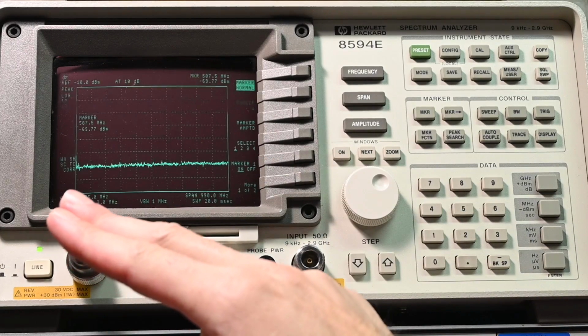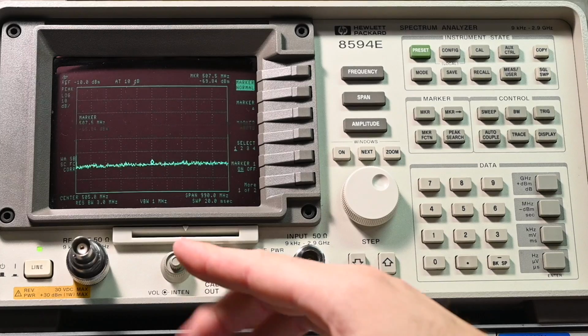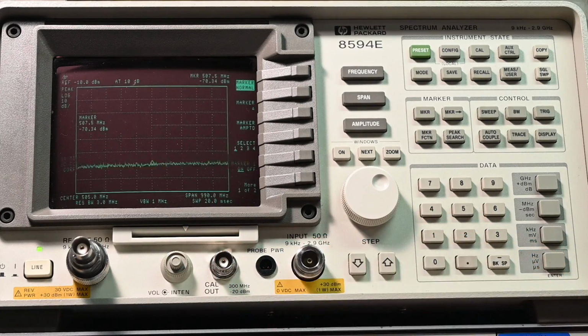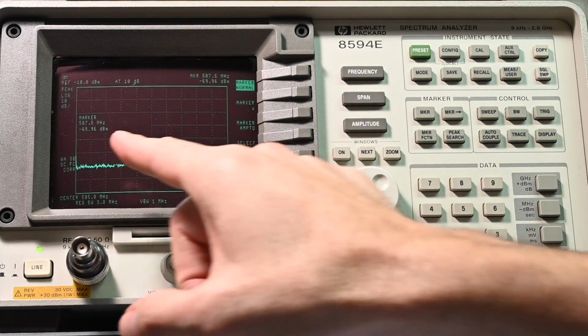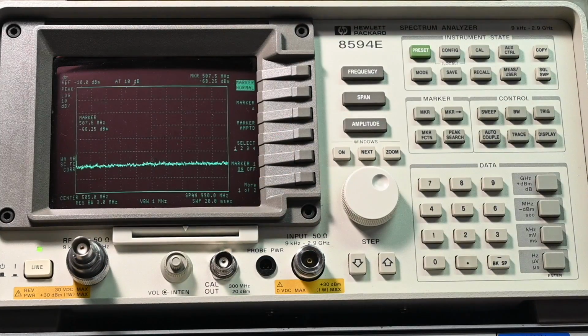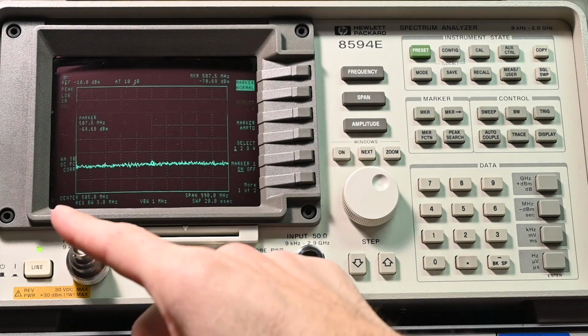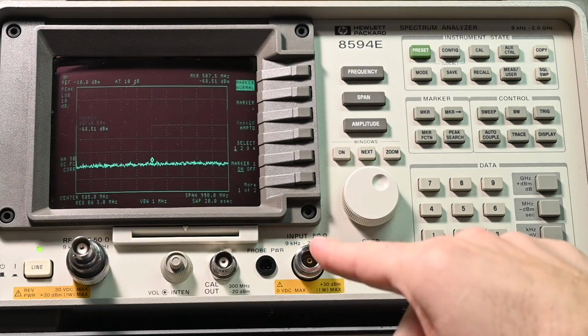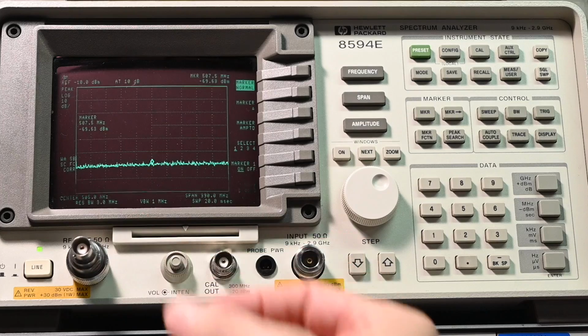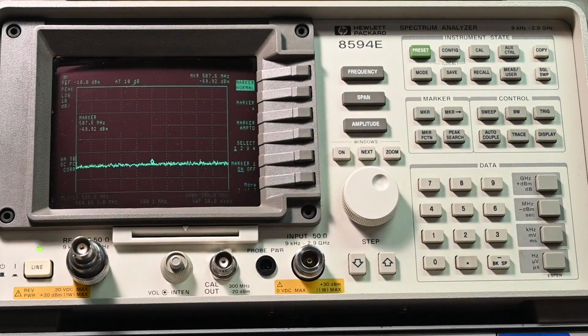So the output from the tracking generator goes into the device that you're testing, and then out of that device you go back into the input on the spectrum analyzer, and then you're able to see the response on the display. So keep in mind that on the spectrum analyzer, this is frequency on the horizontal axis and the vertical axis is amplitude. So, for example, if you had a piece of very high-quality coax, maybe a short section just from the tracking generator over to the input, basically a flat response. Again, if it's very high-quality coax, no attenuation or very negligible for a short section, you'd actually just see a flat line or very nearly a flat line.